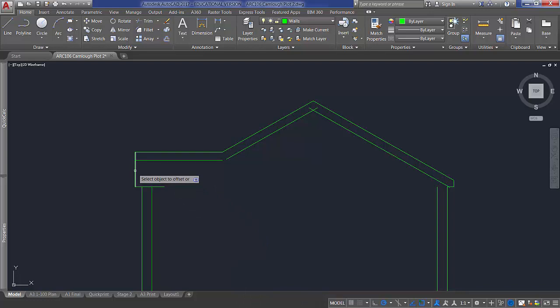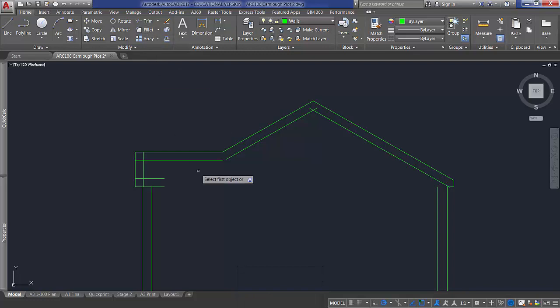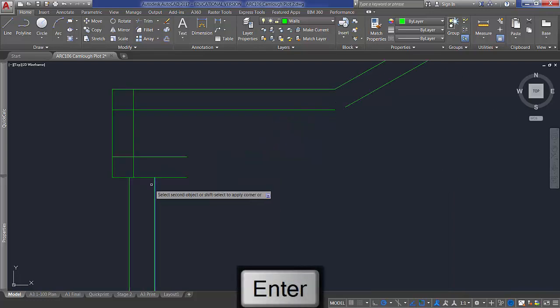And then in this case we are cutting through basically a bit like a verge detail in some cases, so let's just offset like that and 250 again this way. Okay, and if you have the fillet tool available and you just check that the radius is set to 0, you can use it like so just to trim some of these lines quickly.